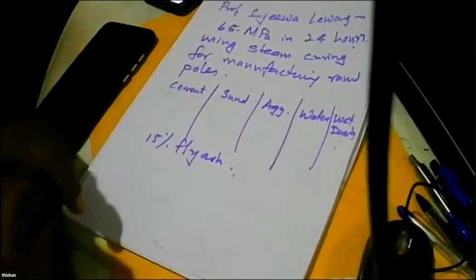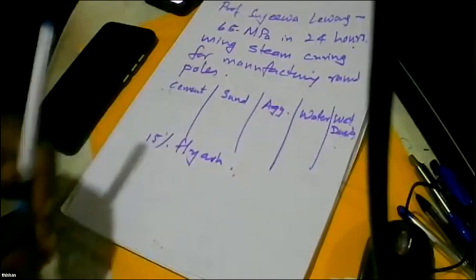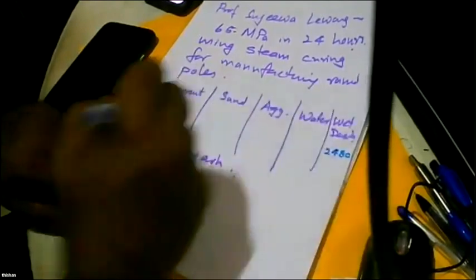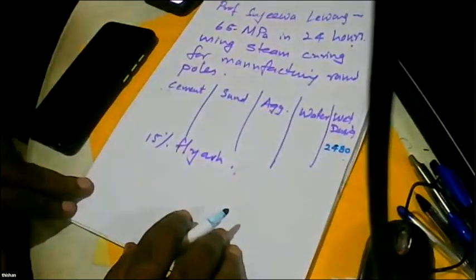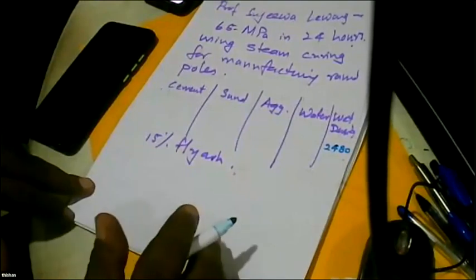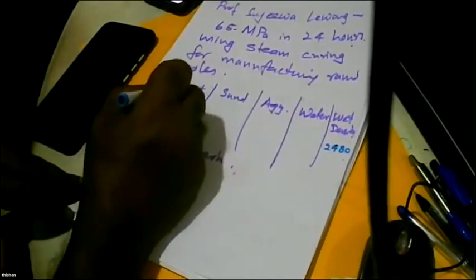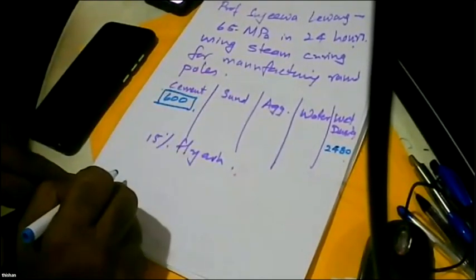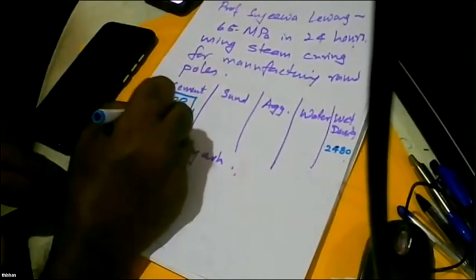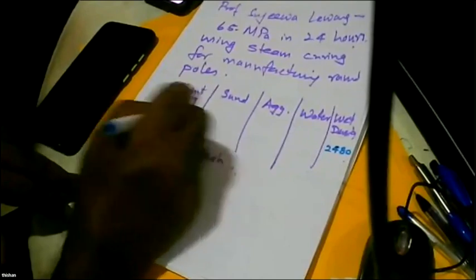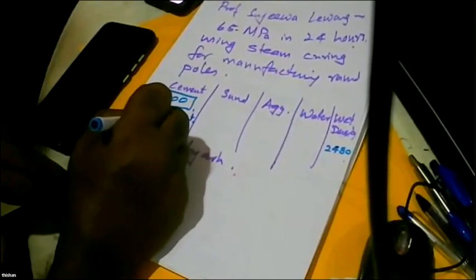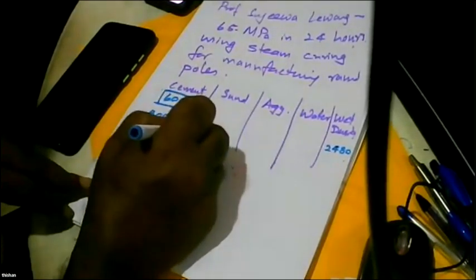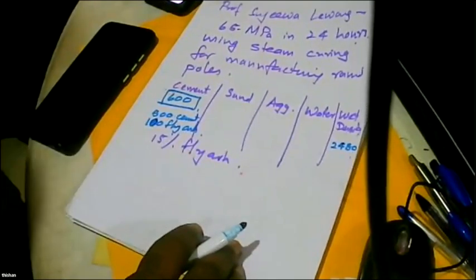So I started plugging in numbers. I said okay, 2180, because I'm going to use some fly ash, and fly ash has a lesser density than cement particles. And so I'd like something like 600 cementitious material. So I said, okay, 500 cement, 90 fly ash or 100 fly ash, just above that. Because when it says 15%, you need not be exactly 15%.